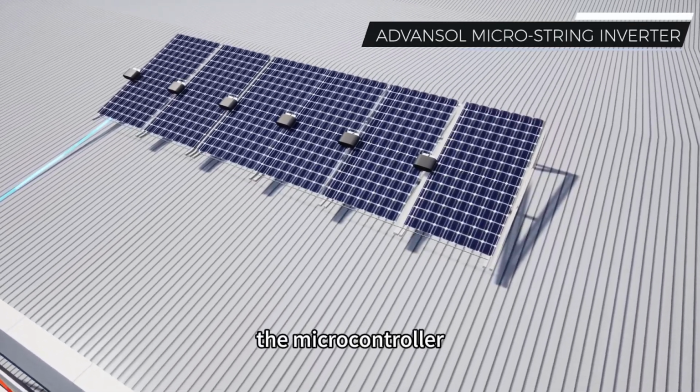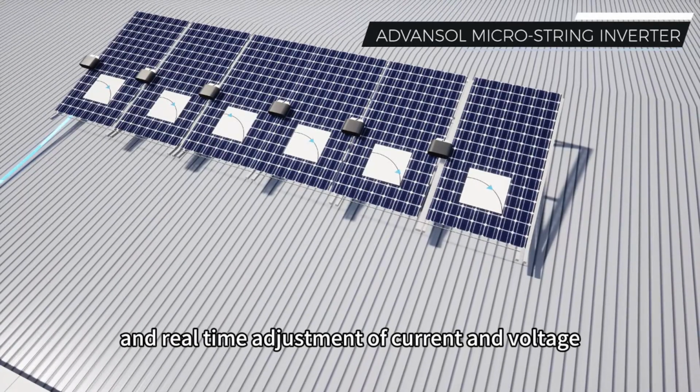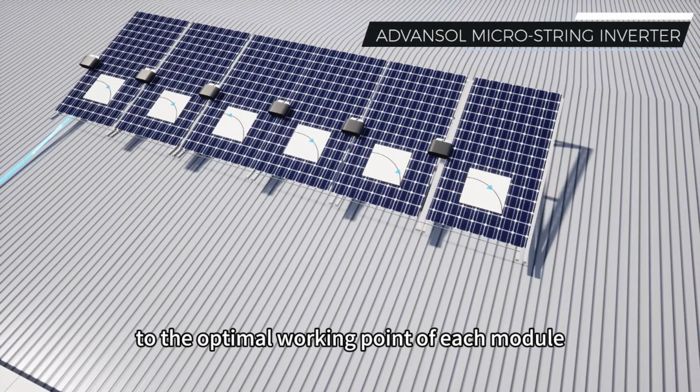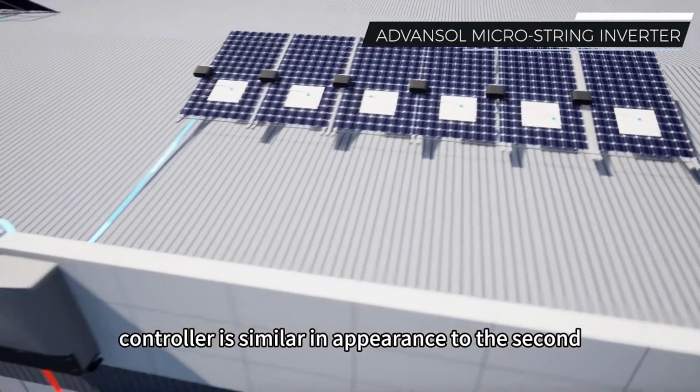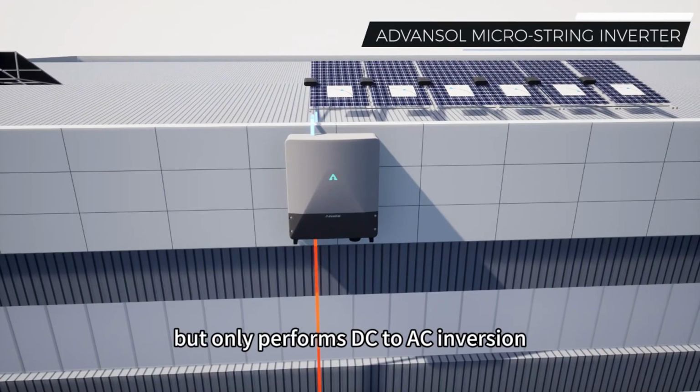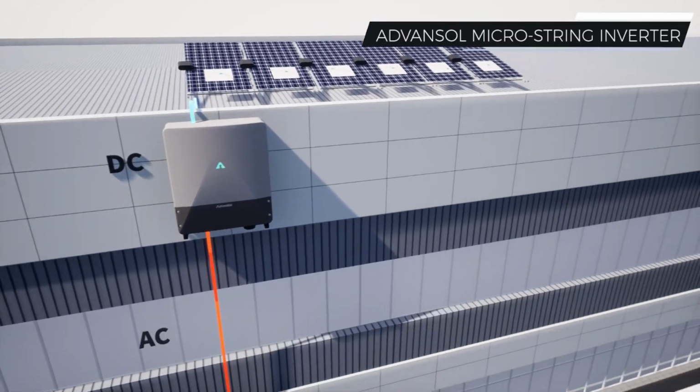The microcontroller enables module-level data tracking and real-time adjustment of current and voltage to the optimal working point of each module. The string controller is similar in appearance to the second-generation inverter, but only performs DC to AC inversion, grid connection, and data processing functions.